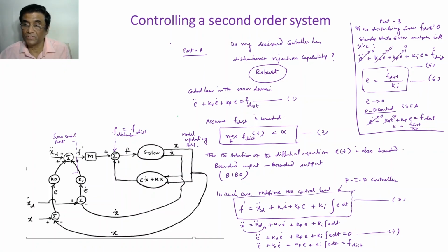If it is not constant, even then you have some freedom to minimize it. So the PID controller preserves all the facilities of the PD controller, but it's one step ahead. But again, as an engineer, you should optimize everything. If you are not expecting disturbance in your system, then go for the PD controller, proportional derivative controller. That is sufficient.